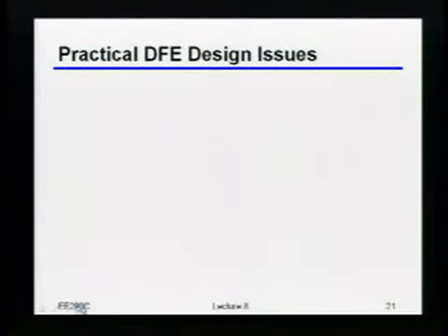Okay? So even when you do that, of course, you're still going to want to do a DFE. So you just need to keep track of when you start doing these interleaving things. That's going to interact with how you end up building the DFE. The key thing to keep in mind is that, generally speaking, the settling constraint on the DFE doesn't really change. So if you start doing interleaving, at some point you may just be spending more power without actually saving yourself anything in the comparator itself.